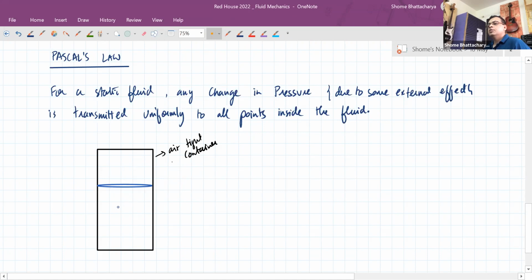Okay. But before sealing the container from above, we had not removed any of the air. So its above part is containing air at atmospheric pressure. Okay. So then you can see that the pressure at any point inside like this, which is at a depth of h, in this situation is equal to atmospheric pressure plus rho gh.